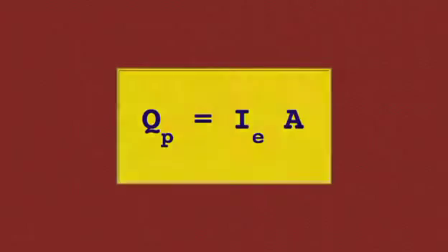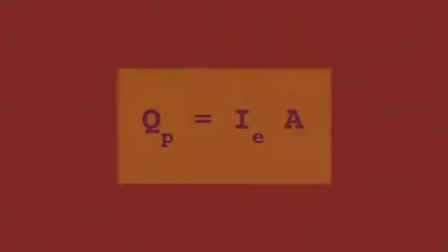The runoff coefficient C is the ratio of effective rainfall intensity to total rainfall intensity. Therefore, the rational formula is a statement of runoff concentration, where I_E is effective rainfall intensity, and Q_P is peak flow, equilibrium, or maximum flow.